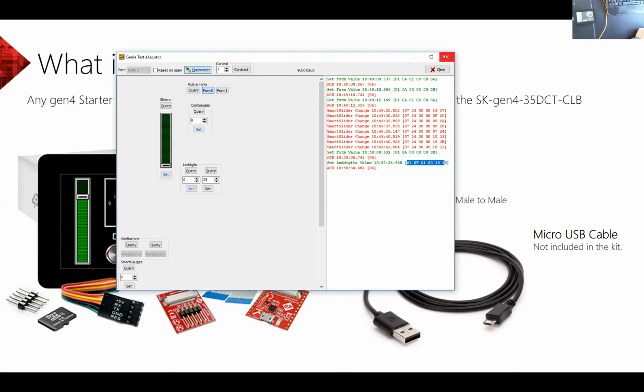It's quite easy to do and quite fast to learn. And when you have the main idea working for you, then it's easy to go and prepare a lot of your custom widgets and so on. What you previously had to do without the Smart Widgets editor, you would have to create everything in Photoshop, all the different iterations. But now, if you want to change the background of the gauge, all you have to do is go to the Smart Widgets editor and replace the base layer with whatever alternative background you wish to have.